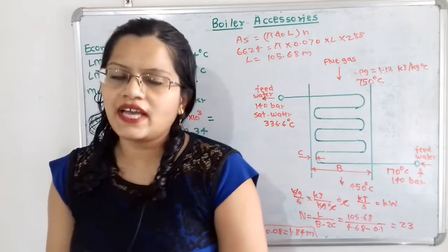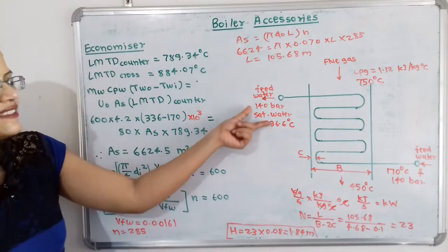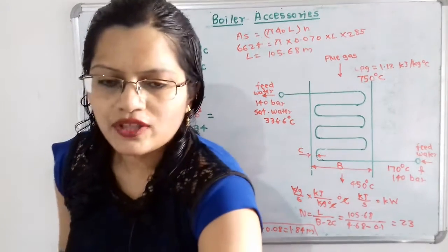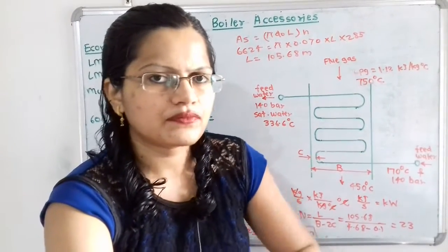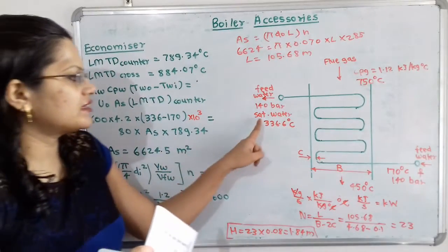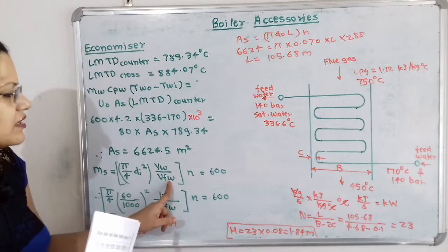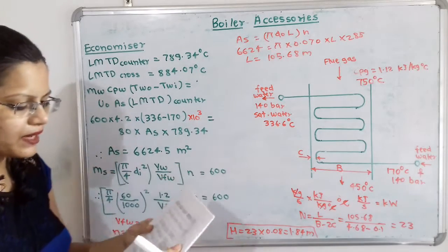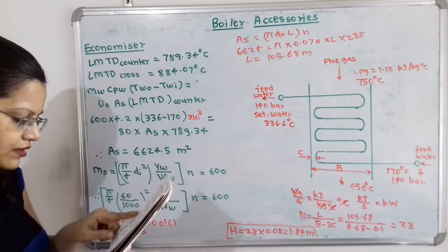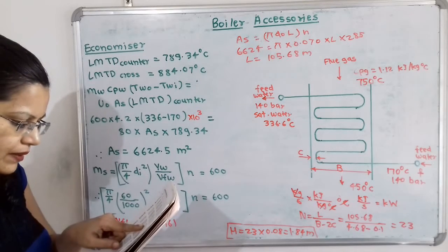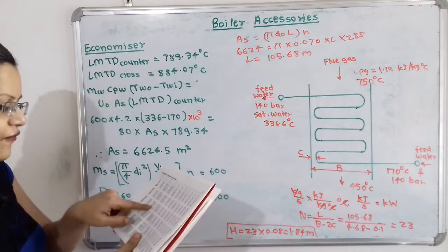Now what is Vfw? So this Vfw we have to use for this saturated water. So for this saturated water, again we will use the steam table. So how we can define this Vfw? So what is the given condition? So given condition, that is 140 bar. So again we will use the pressure table, and for 140 bar, here what is the value of Vfw?